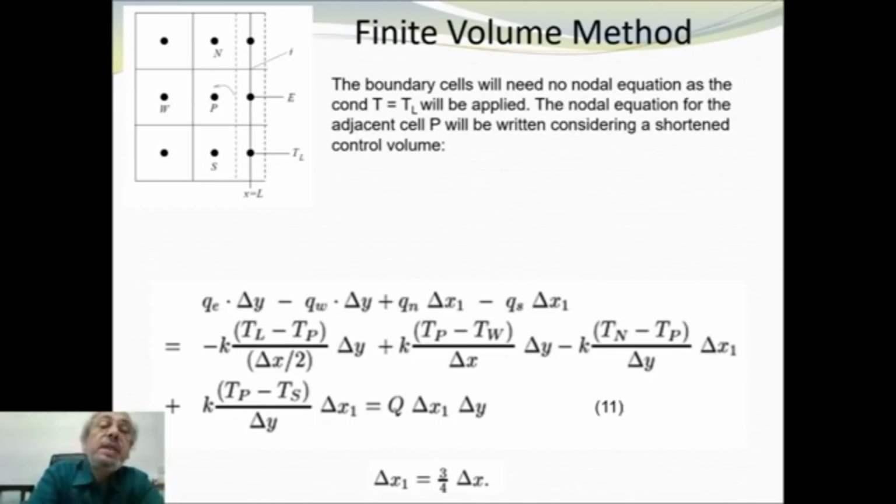So rethink about it, how the boundary condition, when it is Dirichlet, is defined, and since it is directly on the node, no nodal equation is generated for these points, but for the inner points, for example, when this is P, we have come to know what the equation should be. So the philosophy is the same, heat flux in this direction.